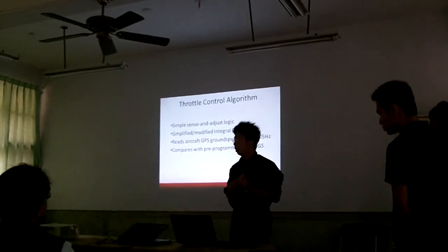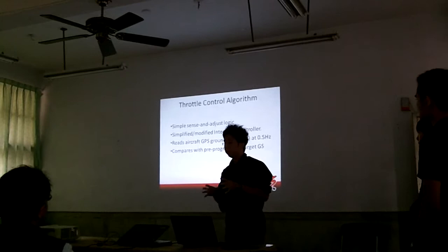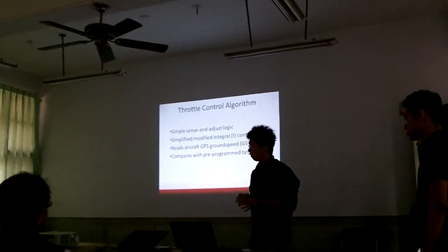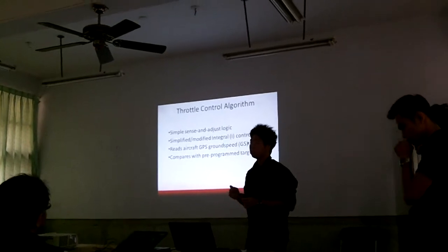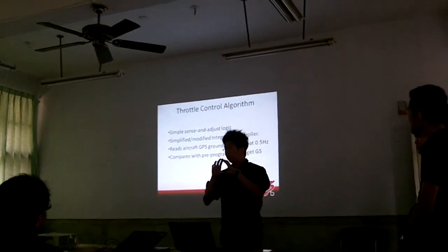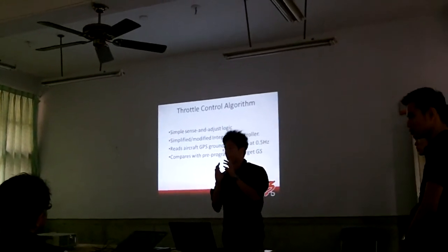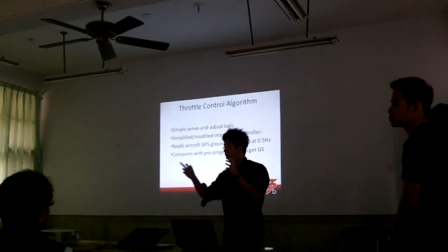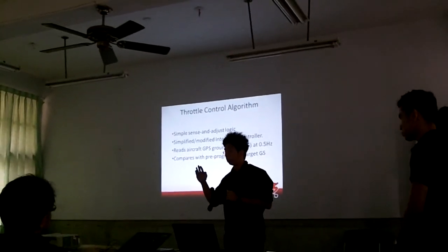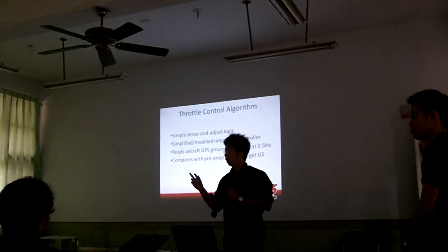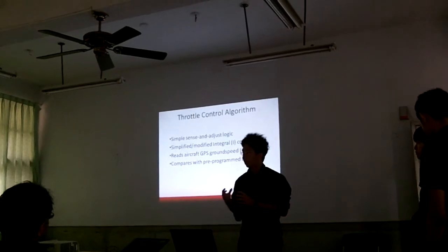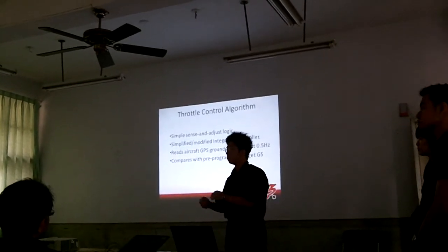So for us, without airspeed sensor, the default code in the APM flies at a speed that is controlled by its throttle settings. And the control of the throttle settings is such that the output throttle is cruise throttle plus a few other variables that are defined by its current altitude and its required pitch. So there is no variable component inside that allows the default code to allow the plane to fly at any given speed that you want.